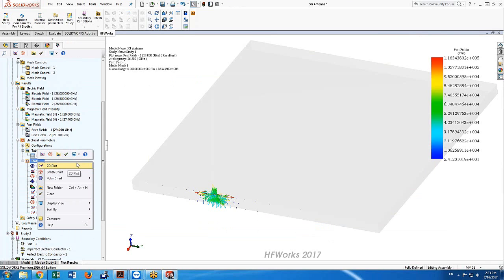All right, and so I can keep plotting, and everything I want to plot, I could plot all of the antenna parameters as well as the circuit parameters, because in this case I have only one port, but an antenna feed could have many different ports. It doesn't have to be just one port for the feeding.